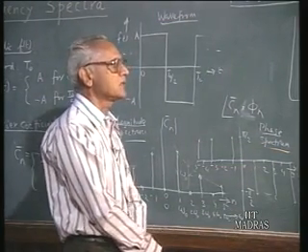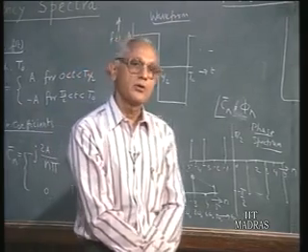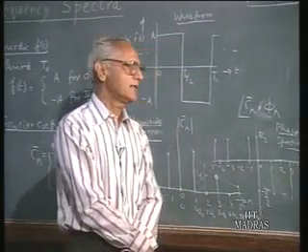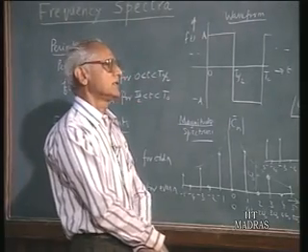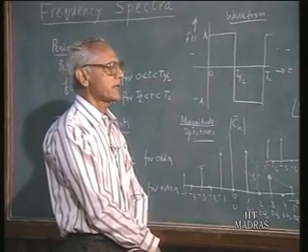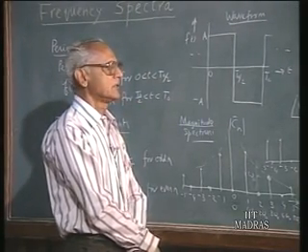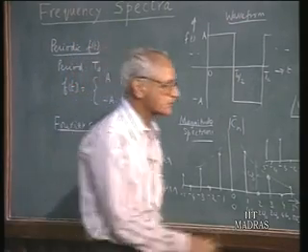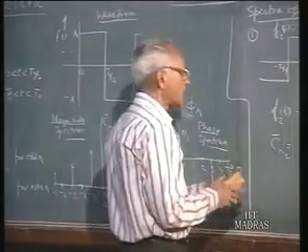Usually we are interested only in the magnitude spectrum because we would like to know the relative proportions of the various harmonic components, and therefore we can say that the magnitude spectrum is invariant under the operation of shift in the time axis. Let us take a second example.